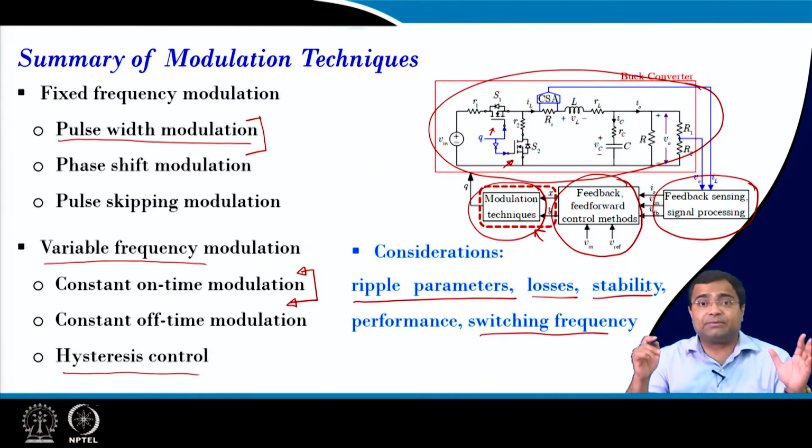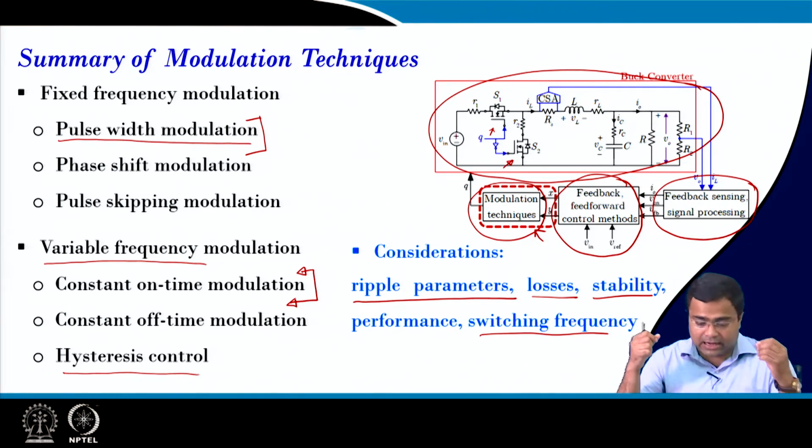Another aspect is the stability, that means which control technique will offer inherently current loop stability or maybe enhanced closed loop stability, and under digital control, when we consider one by one their digital version of this modulation technique, we will find that the stability can be affected under different modulation techniques while considering the sampling delay.